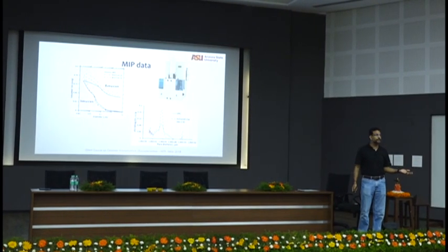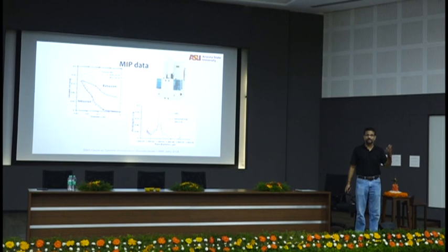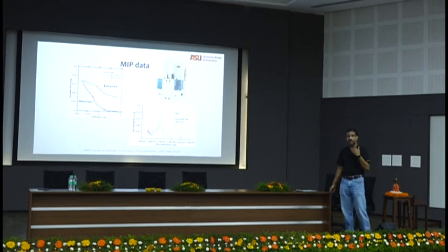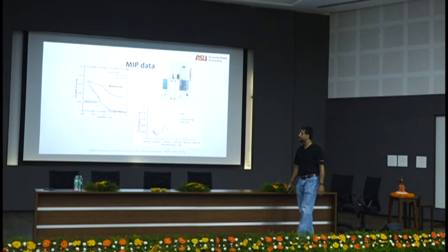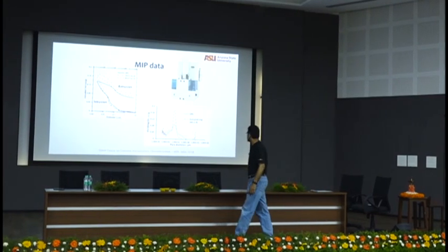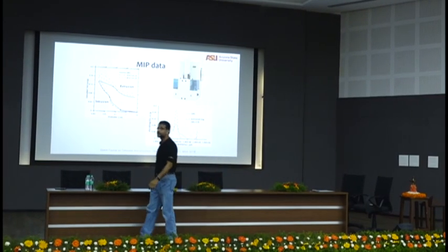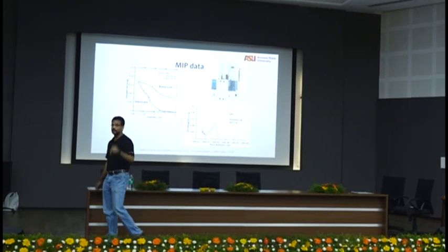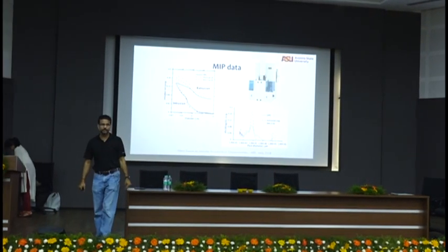Again, you can differentiate between mixes that have fly ash, mixes that have silica fume, mixes that have something else, alkali activated slag, alkali activated fly ash. With a little bit of calibration, with a little bit of knowledge about how this happens, now this becomes a very powerful tool to figure out what microstructural changes happen because your composition has changed.